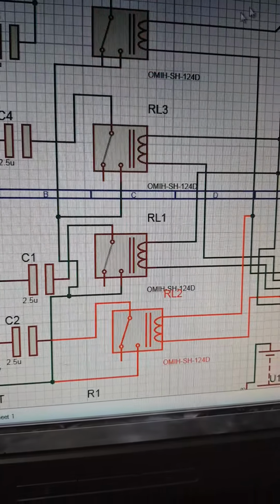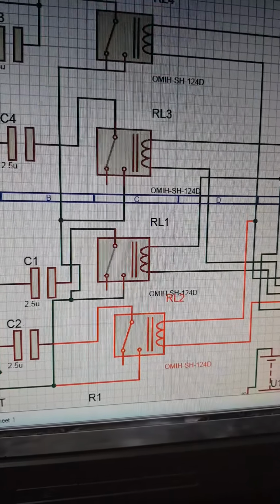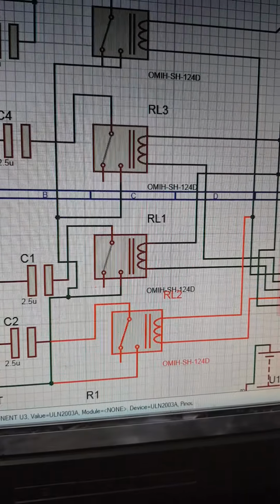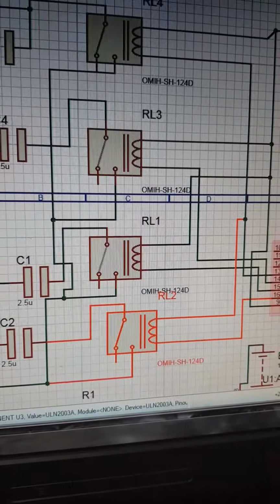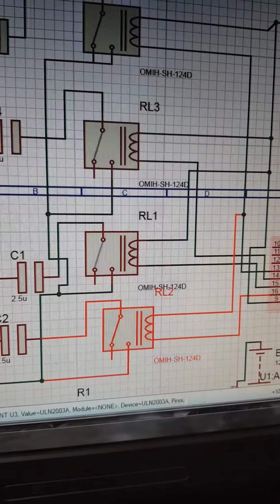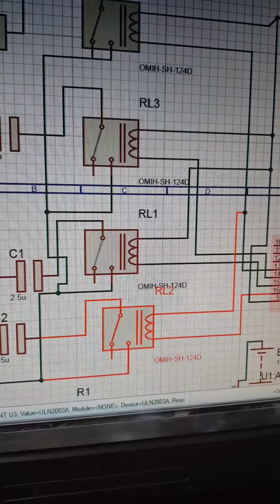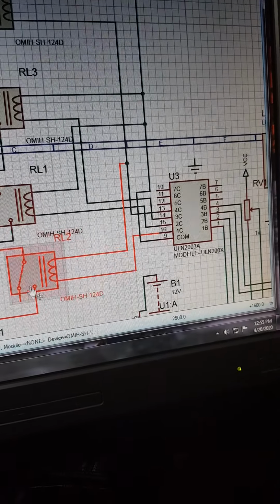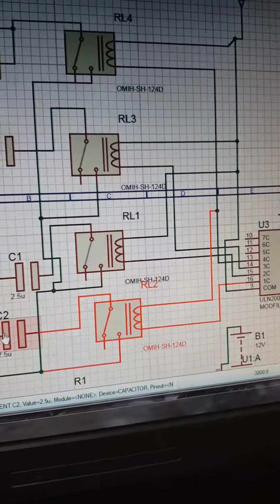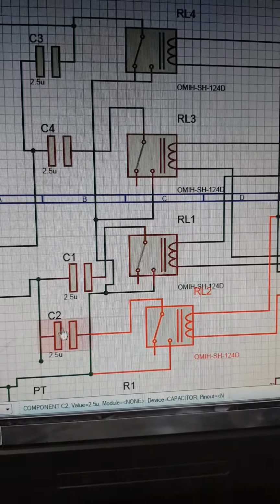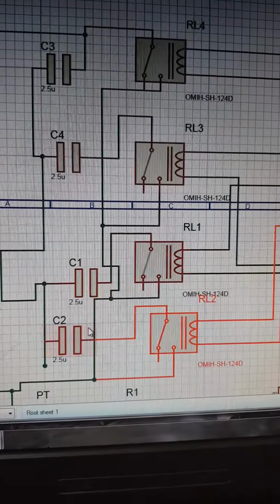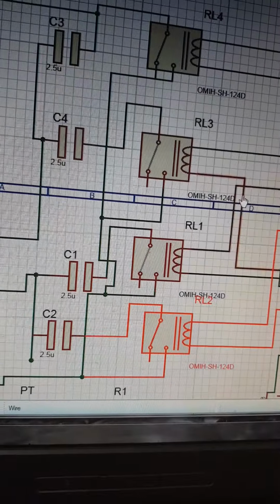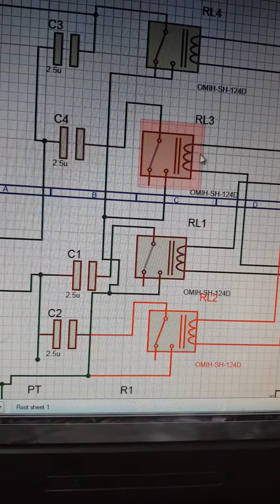So this makes it not work. Even when you send the command here by means of a current signal, asking for any of these coils to be excited so that you can engage this capacitor and start your power factor correction, that cannot be done because the voltage demand of your coil is higher.